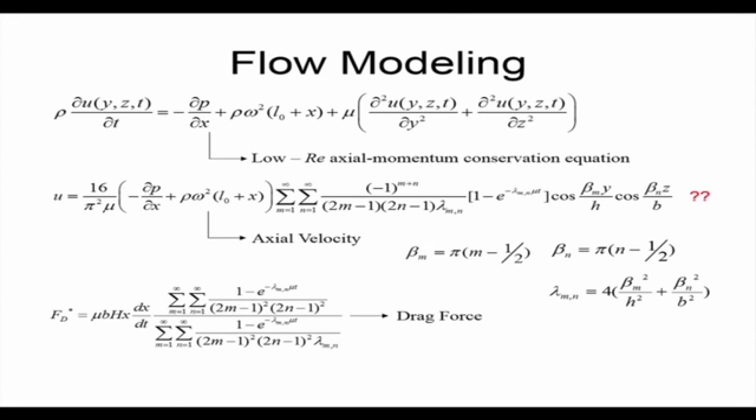So how to model the drag force? What we have done is we have considered it just like a pressure driven flow, where the pressure gradient is augmented with the centrifugal effect, right. But we have used this with an approximation, and technically this expression is wrong. Can you say why is this wrong? That is why I have put a question mark here.